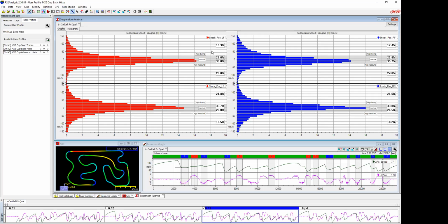Okay. Shock tuning, if it was easy, everybody would do it. We'd all understand it fully, and we'd all be doing it, right? There is some information here to play with. Okay. Joe mentions a question that has just popped up there. On a 3-way adjustable shock, do you want the numbers to be 33%? No, that's the way that our software is breaking it down, only into the 4 quadrants. Your 3-way adjustable shock is allowing you to adjust across the 3 different positions: low speed, mid, and high speed.